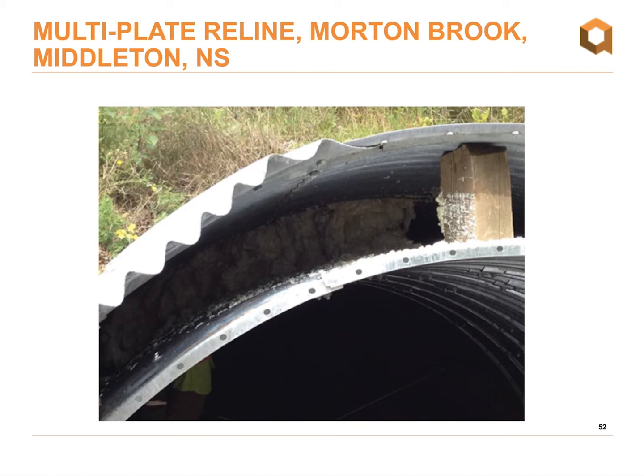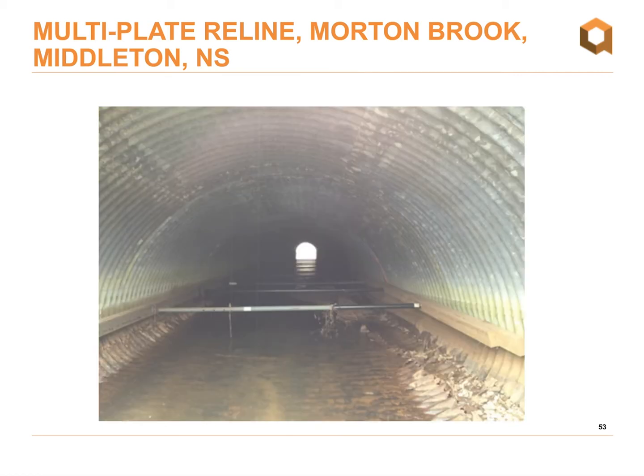This installation was not a traditional one for Armtec, as instead of using flowable concrete grout, TIR decided to go with an expanding polymer foam to fill the annulus between the reline and the host structures. Using this method allowed the owner to grout the structure as it was being installed and without the need to construct bulkheads at either end to retain the grout material. Once we had the structure erected to the portion with the horizontal bracing, the structure was torqued and foamed. This provided a fully functioning structure behind the workers, which could have served for an escape tunnel had the structure began to move during construction.